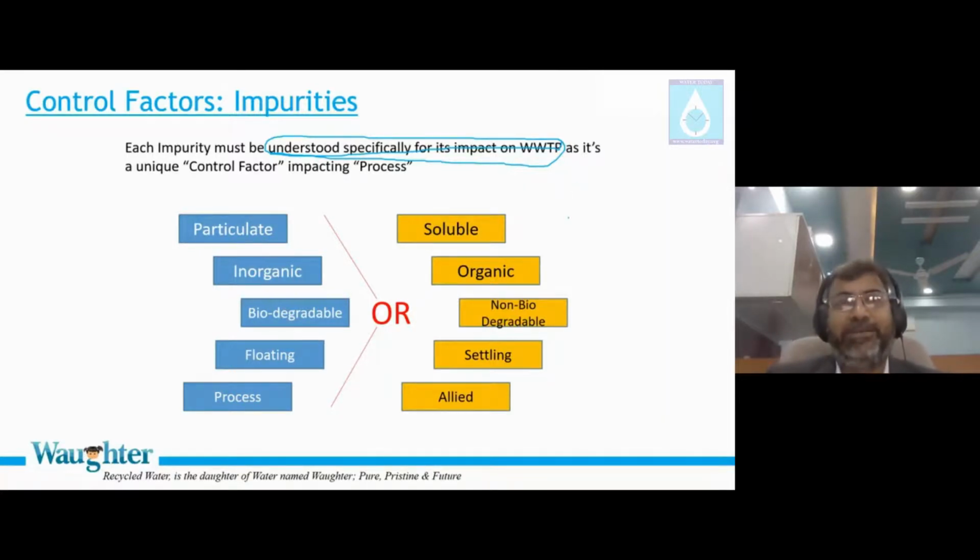I cannot present the case study of that because that's a project where I have some kind of confidentiality obligation. So I'll not name it, but I'm just trying to say it was an airport and it was designed by a beautiful consultant from South India. He's very knowledgeable in his field and all that. But he designed it the way a sewage treatment plant is designed. And believe me, guys, when this plant was getting commissioned, that day the COD was 230, but the ammonia was 354. He said, what the hell? This is not sewage. And he was absolutely right.